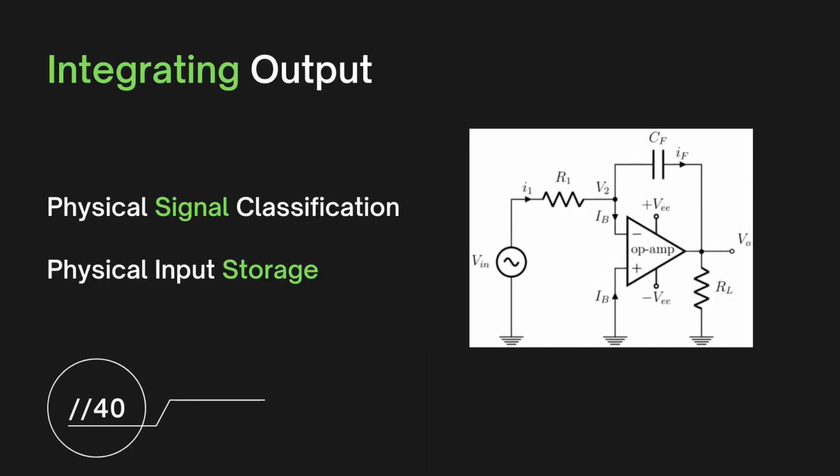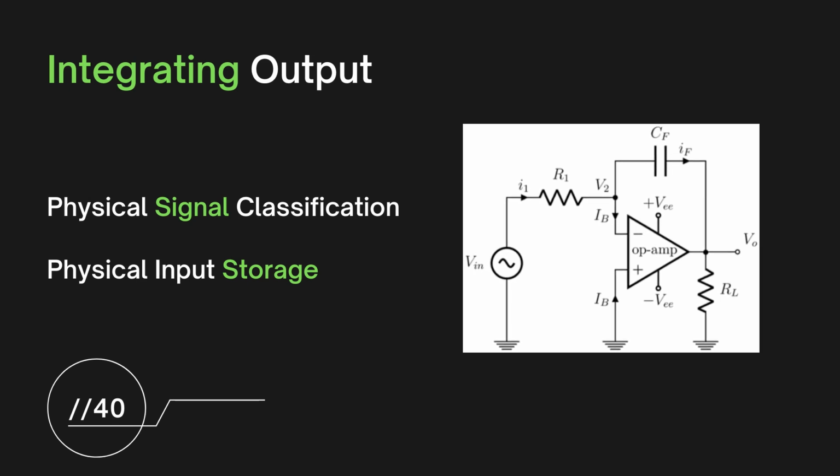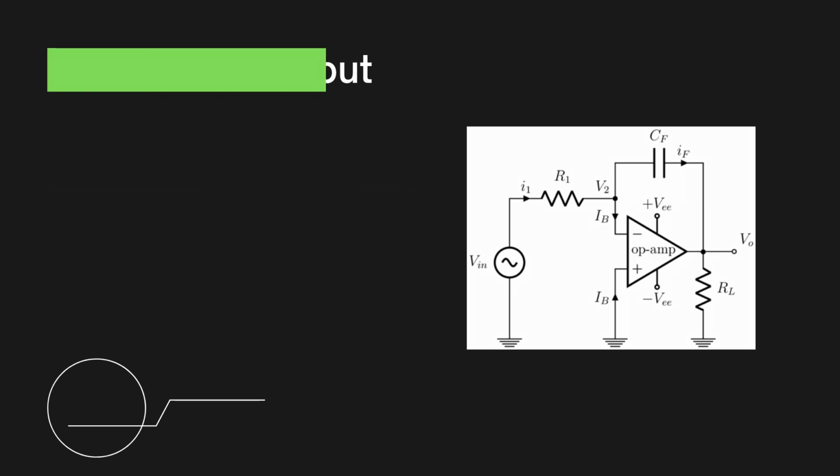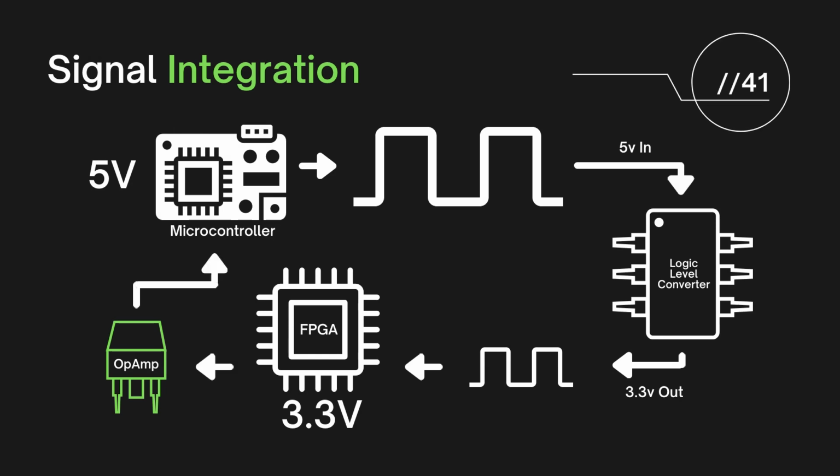Additionally, an integrating operational amplifier was added to the setup to magnify the output signal of the FPGA while simultaneously integrating the output voltage for simple ADC readout by the microcontroller. Simply put, this device acts as a binary memory buffer for the microcontroller, as the latter does not have enough memory to store hundreds of thousands of microseconds worth of waveform data. The integrating op-amp is then situated between the FPGA and the microcontroller, and with that, we are now ready to start our experiment.